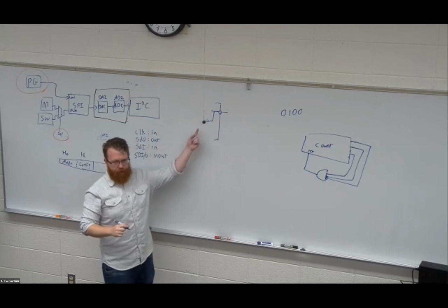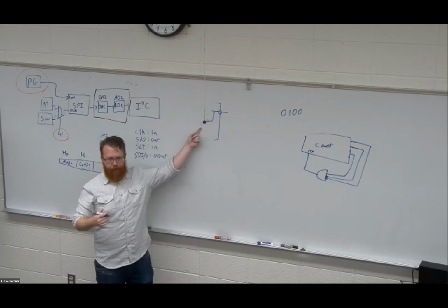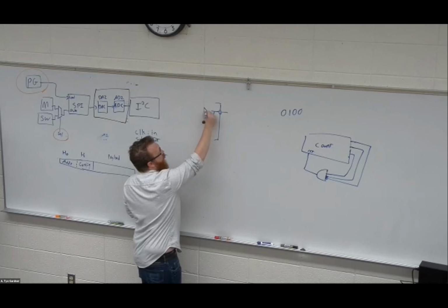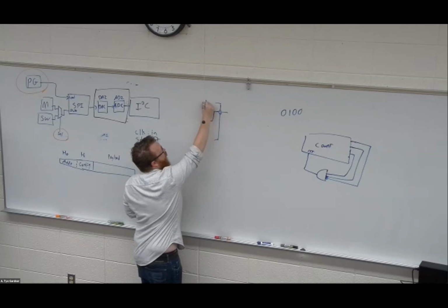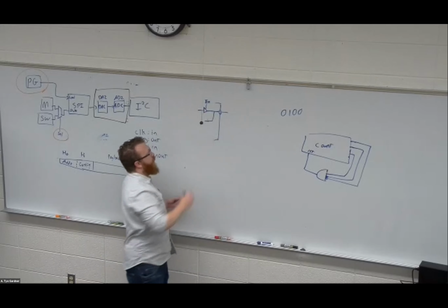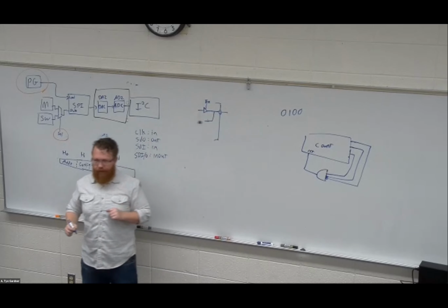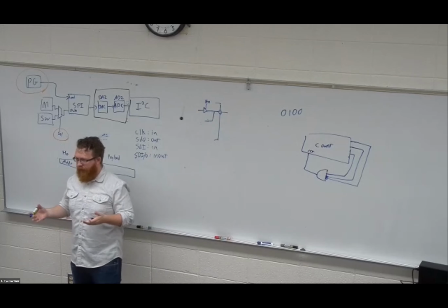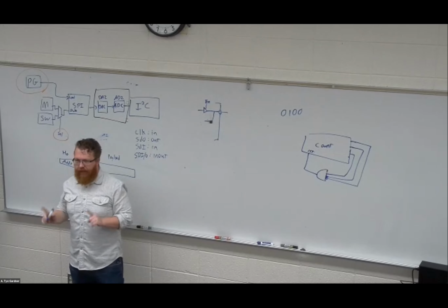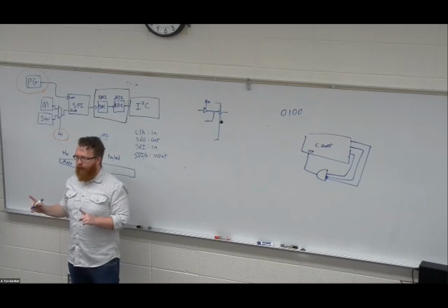It's going to be treated as an input and read things. My output then is going to have an enable signal. This is just an enable buffer. If enable is 0, it's not enabled, and what that means is, in this case, it's going to go to high Z.